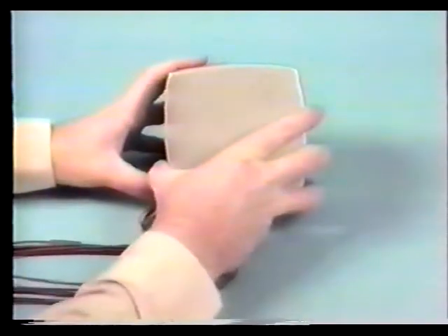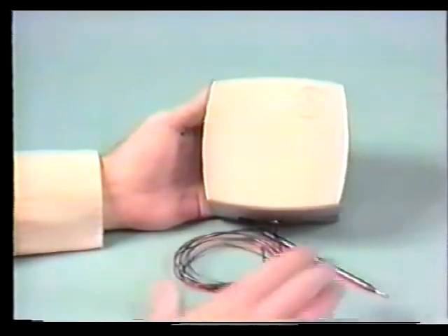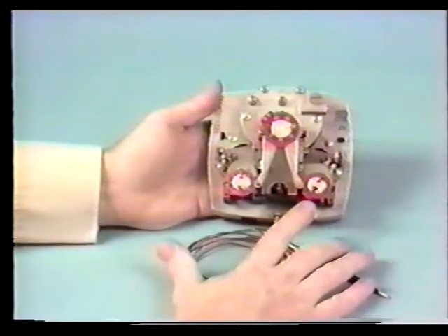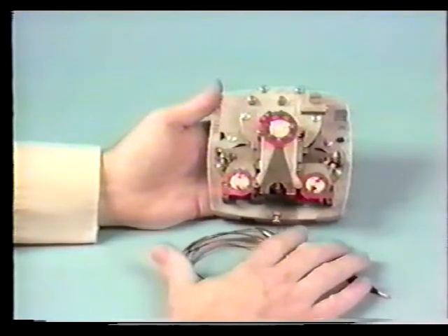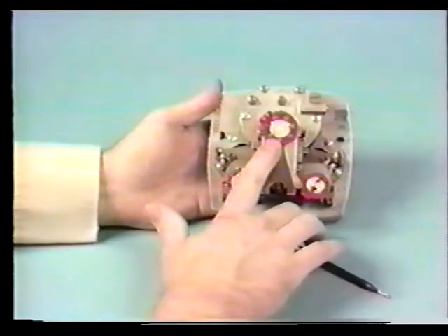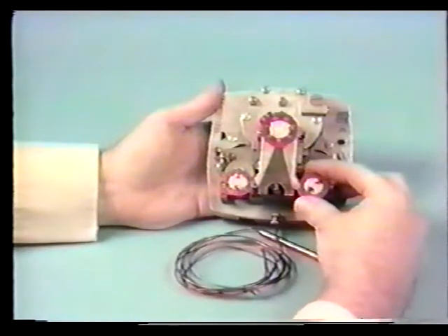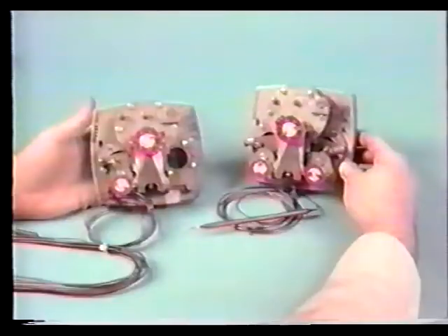Shown here is an example of a remote bulb temperature controller, or master controller. And this is an example of a submaster controller, the difference being the addition of a reset scale, which provides the ability to have an input from another controller, which will automatically reset the set point of the submaster controller over a specified range. This is dialed in directly on the controller itself. These master and submaster controllers had to be calibrated separately.